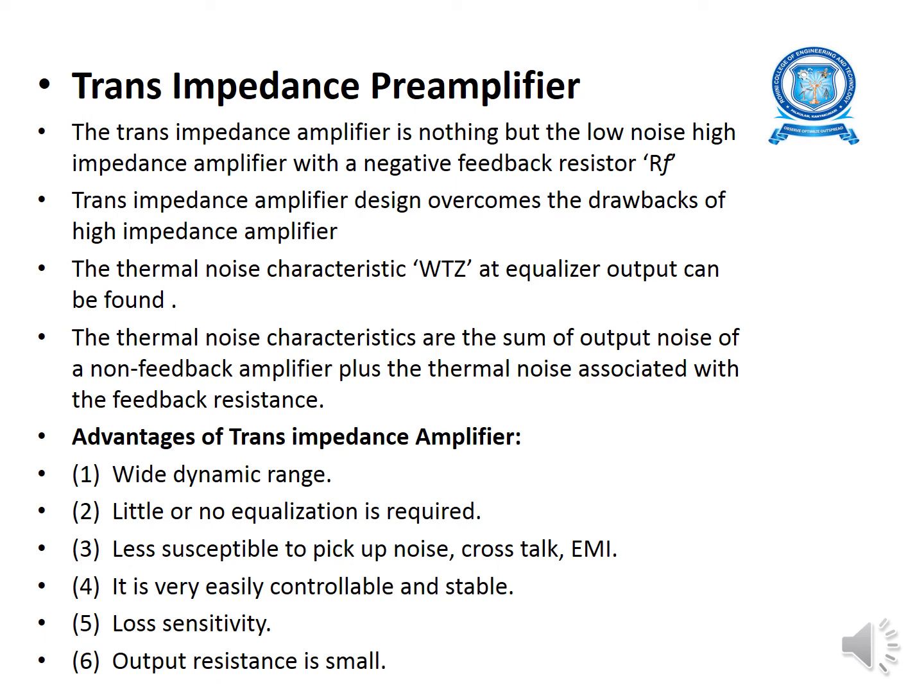The advantages of transimpedance preamplifiers are: they provide a wide dynamic range, little or no equalization is required, and they are less sensitive to pickup noise, crosstalk and electromagnetic interference. They are also very easy to control and stable, and the output resistance is very small.